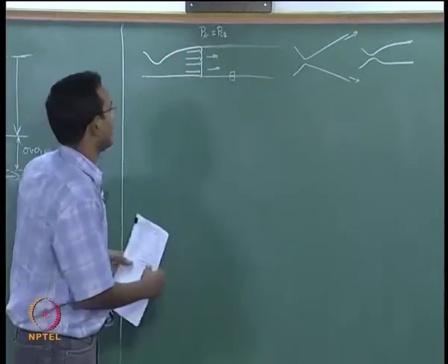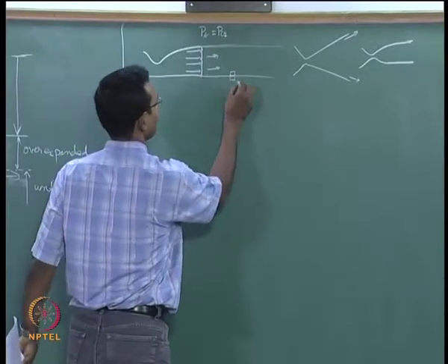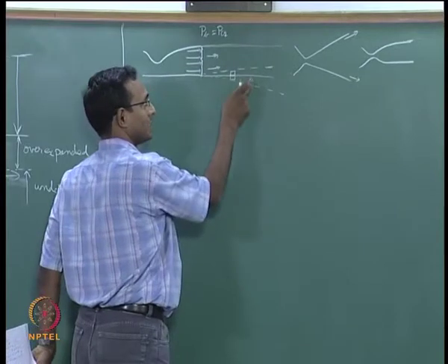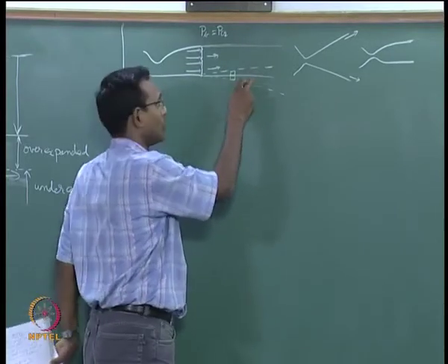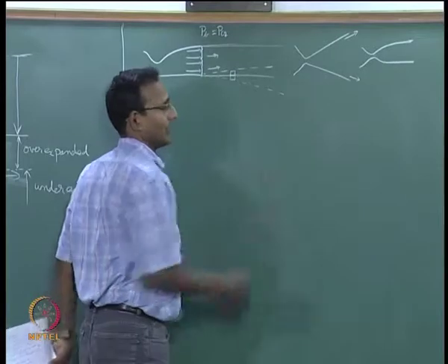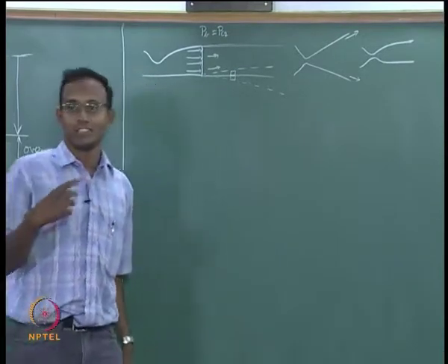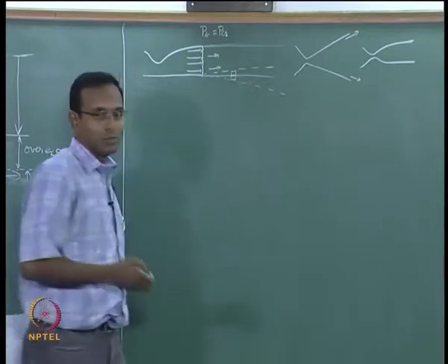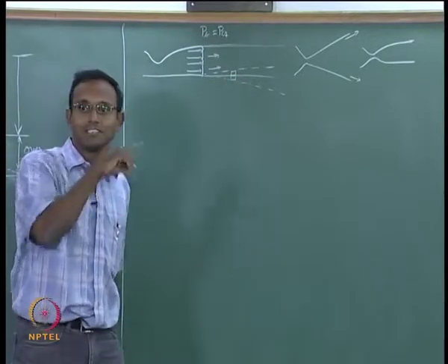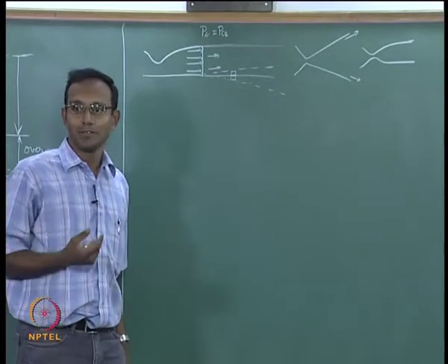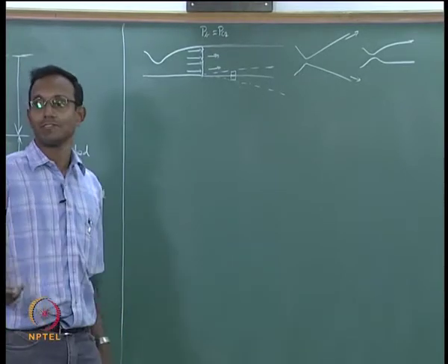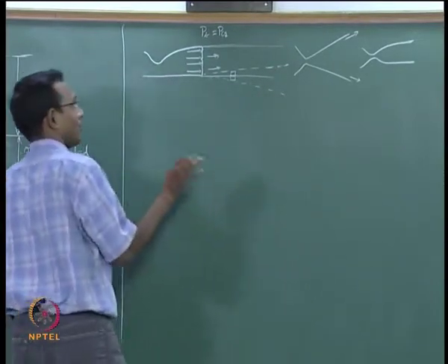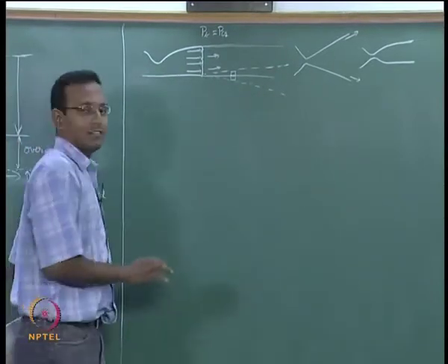In reality, there will be some viscous shear stresses developed in this region, and so this region will become slower, this region will move faster. And so, you are going to develop this whole dotted line region is called the shear layer, region where there is shear forces important. Okay. I said important, I am using careful words. Even other places there will be shear stresses, we can neglect it compared to other forces like inertial forces. Okay. That is the only difference there. Anyways, that is too much of fluid mechanics for today, we will not want to go there. We will still assume inviscid.